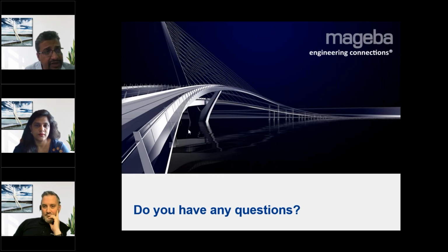Second, Vivekananda Bridge, as Meghna showed in that slide, is also equipped with disc bearing. So it is in use for quite some time in India. As you correctly pointed out, Mr. Selvan, it's high time IRC and MORTH take into account this very popular bearing and introduce it in their standard.